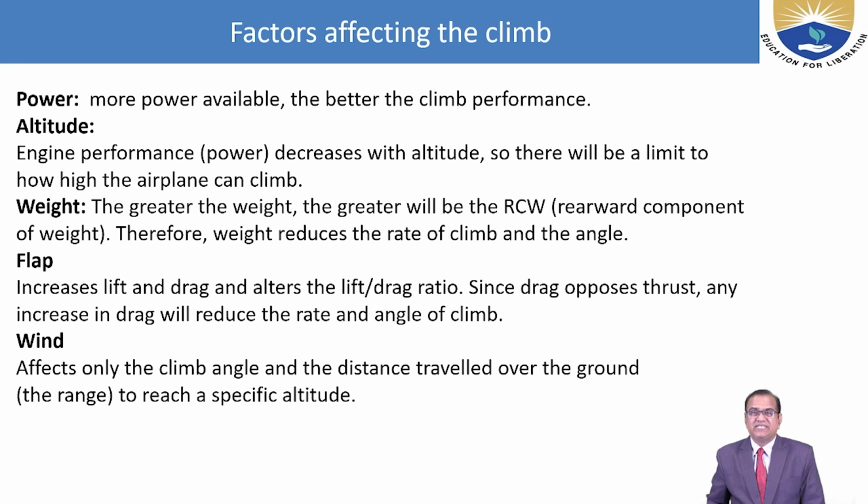Then wind is also a very important factor. The direction of the wind is very important; it affects the climb angle and the distance traveled over the ground, the range to reach a specific altitude. So wind is also very important for the range of the aircraft.